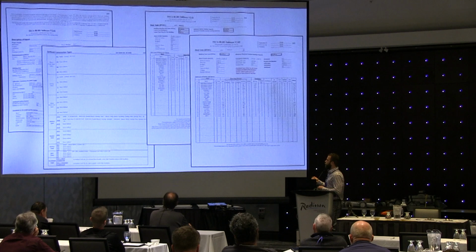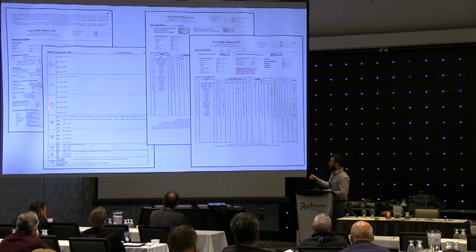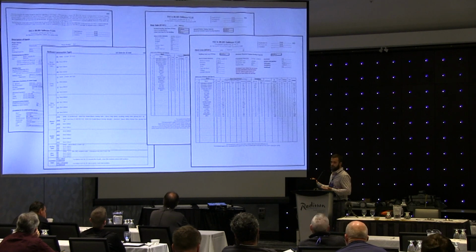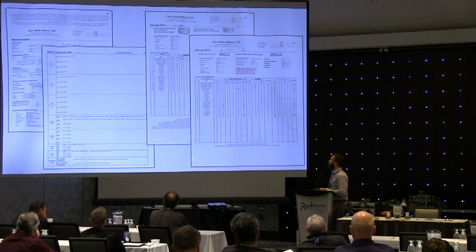But basically how it looks is you've got 1 page over here for input. This is showing whoever's reading the report what went into the project. That's huge, right? Typically assumptions are required at this level all the way through. So you need to know what you're reading, or what these results are from. This defines all the information about your building, and this is about the construction, like the R values of the walls and everything. And then you've got the results over here.